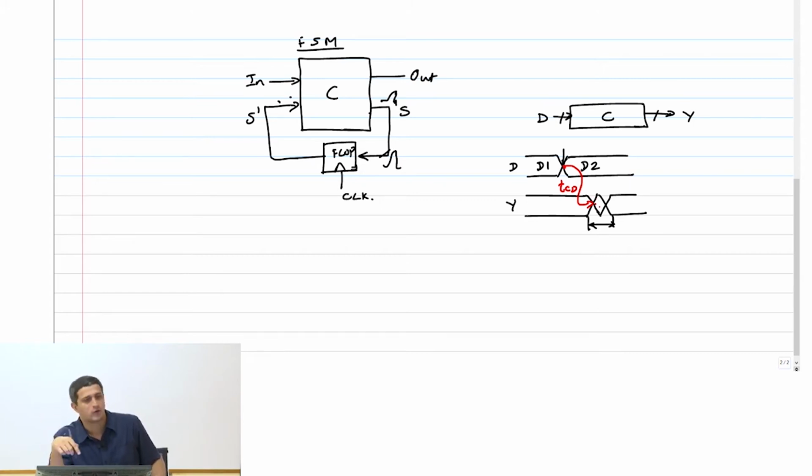The reason we need to do this is, later you will see in a flop based system there will be a clock that changes, there is also data that changes, but the output may react only to the clock, not to that data. So by putting this arrow, we are saying it is a change in this edge or data here that caused the change in the output Y. This change here is called the propagation delay, TPD.